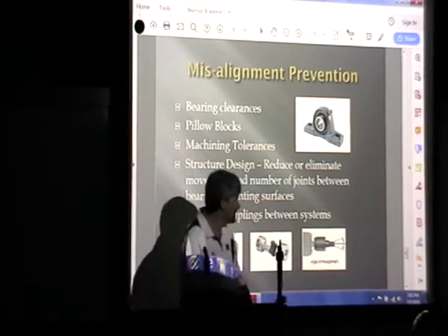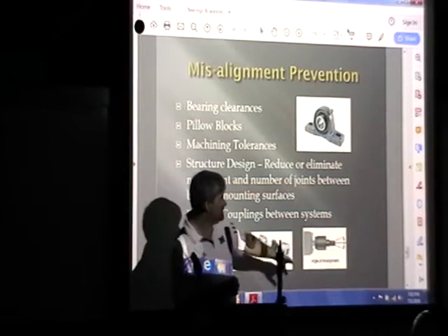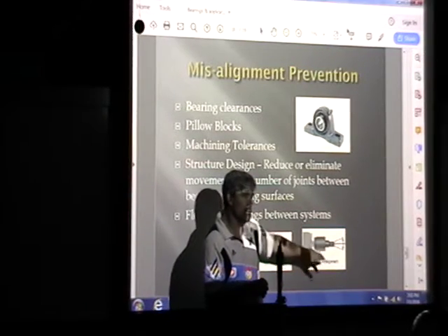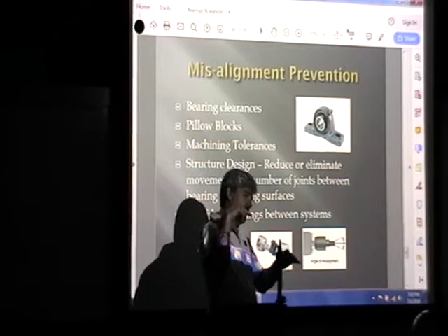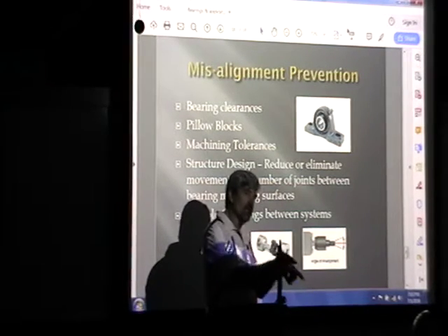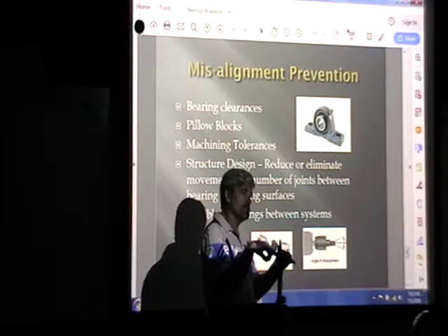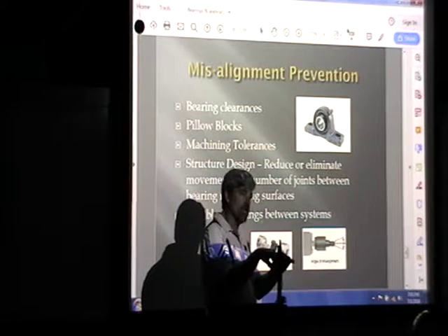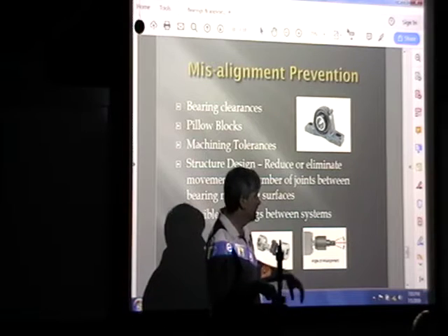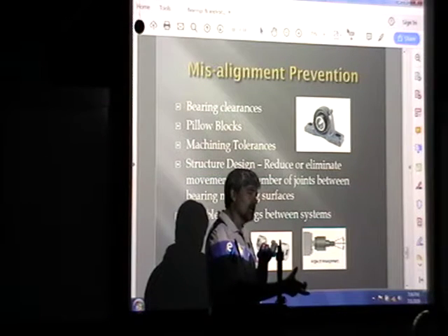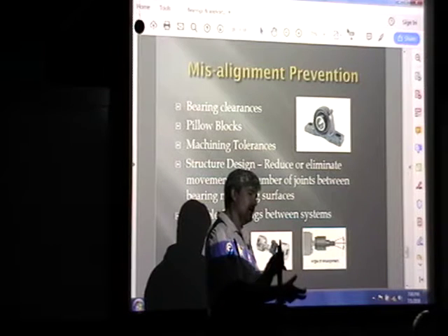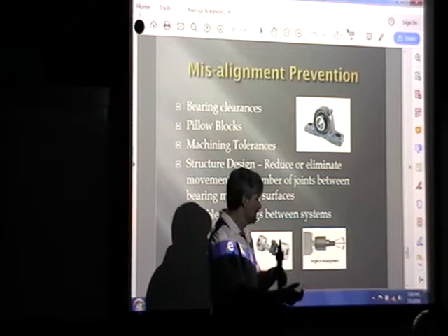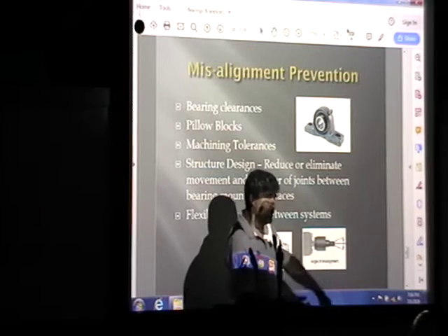This is another way to do that. It's called a misalignment coupler. A lot of times these are used in pneumatics, and the same thing applies to pneumatics. You've got the cylinder actuating, and that's on one linear bearing. Okay, that's still got a front plane bearing on the shaft, and that's actuating. Your load system may have another bearing set, so there may be some misalignment between the load system and the cylinder. So you use this, which is a misalignment coupler.